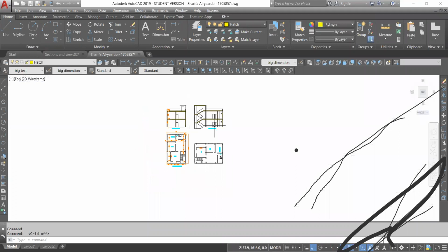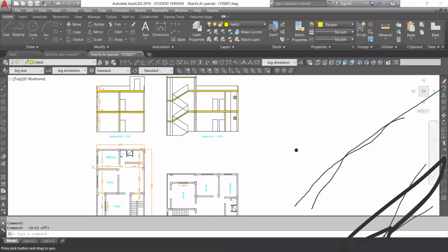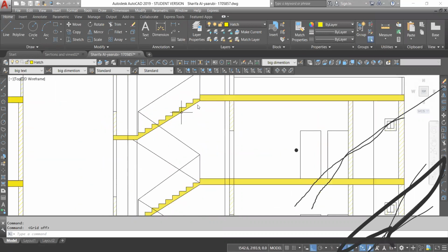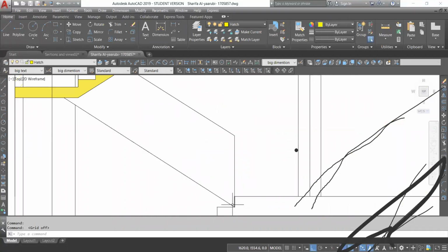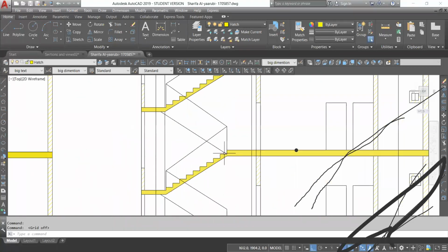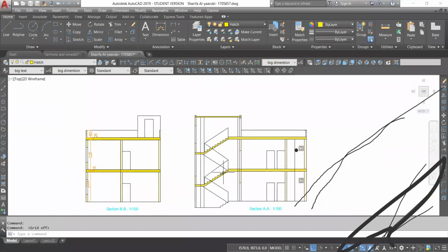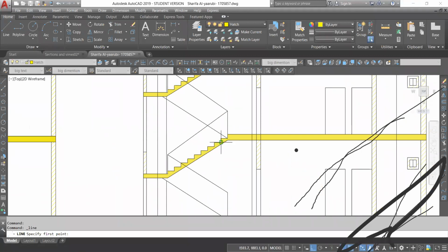I'll remove the grid. If I look at this drawing, first it seemed to be a good one. If I check the alignment here, this is correct. This is wrong. This drawing is not correct. The stairs. Please come back and see the stairs drawing. Same mistake. This line is not correct. Here the drawing is not correct. The offset must be 15 centimeters. It's too much there.